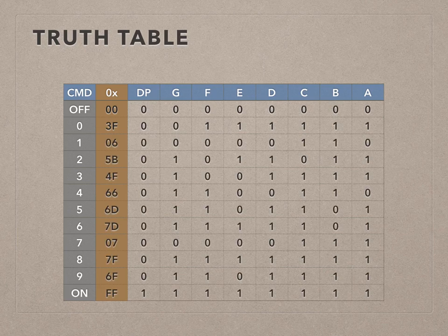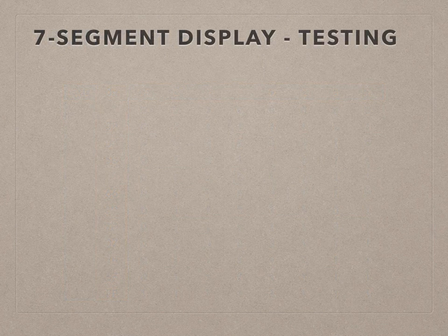The next step is, of course, to test our code and see whether or not we have managed to plug it all in correctly and choose the correct hexadecimal values for our chip outputs. The first command we're going to run is, of course, to set our I/O register direction to be all outputs for the 8 pins. This is done by sending the bytecode 0x00.